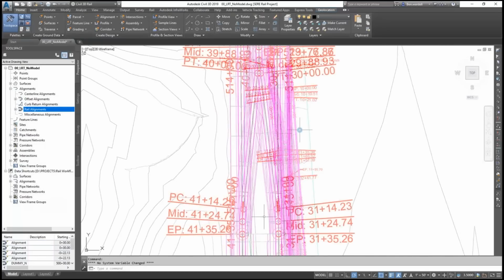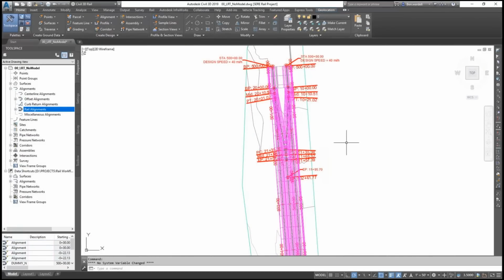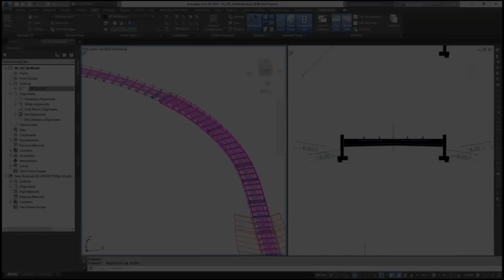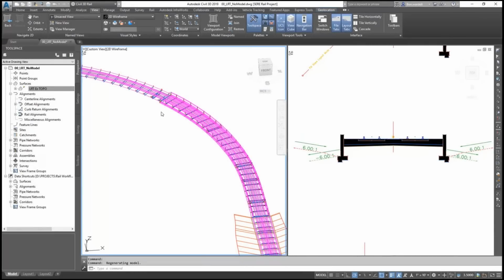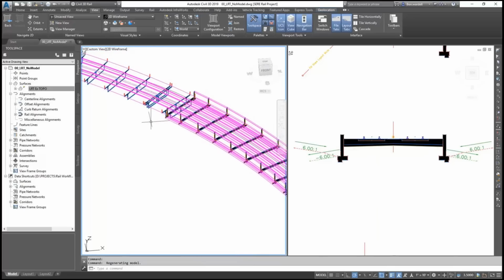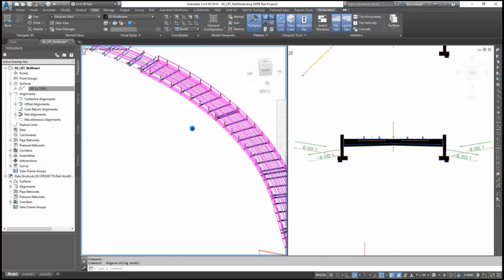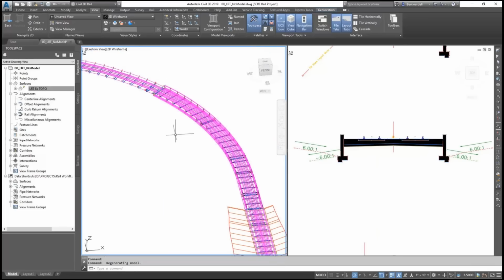So again, I know I'm kind of glossing over a lot of that, but what that did is set it up so that we have our entire assembly. Now this is that area I was talking about before. In this case, it just found existing ground, but we know in this area, we have a bridge, and we actually want to create walls in this area because this whole area is slated for development. So we actually want this to go down to an existing alignment.